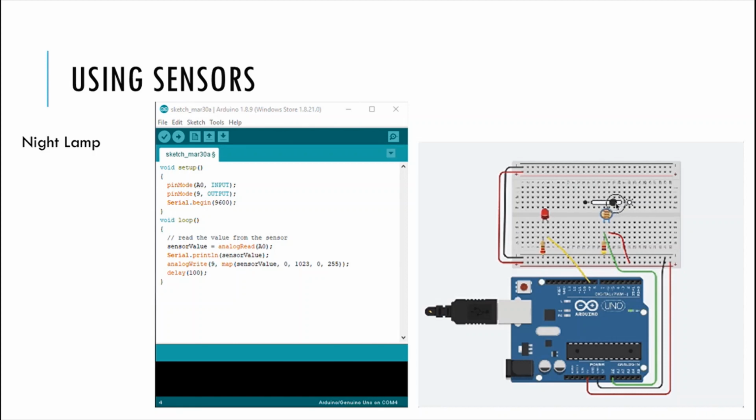Now, as I've told you, the Arduino can deal with analog inputs. Now, as the resistance value changes, signal value keeps changing from 5 volts to 0 volts, and we need to note down the intermediate values. Right? So what we do is we declare A0 as the input.